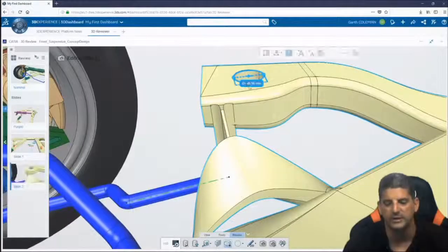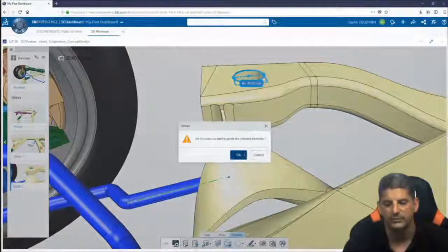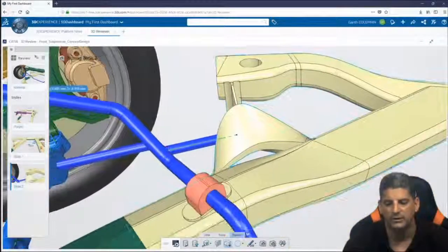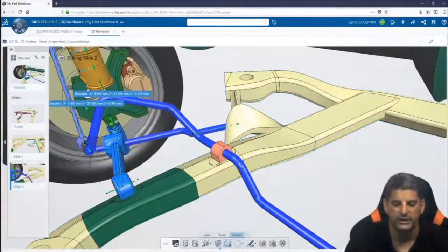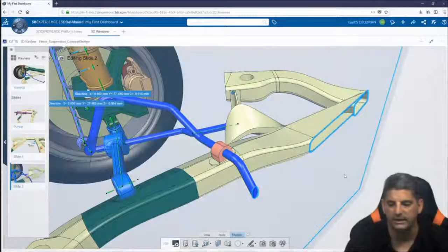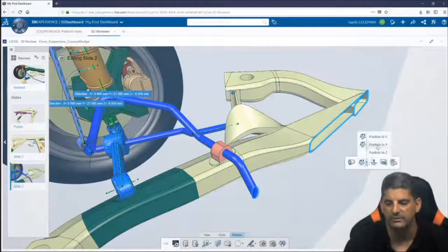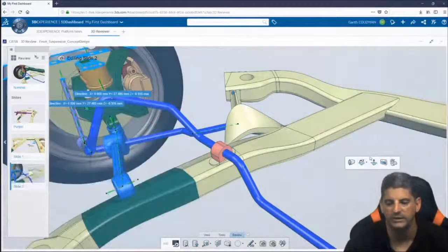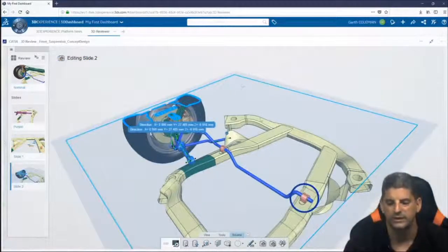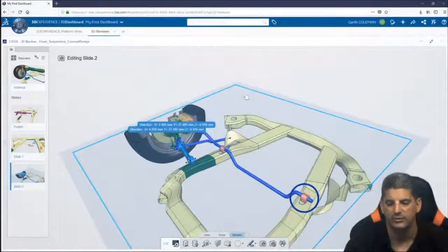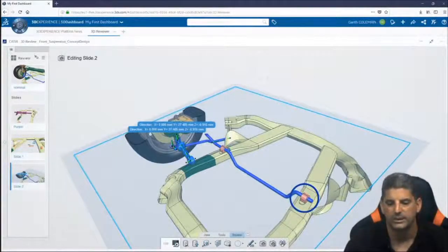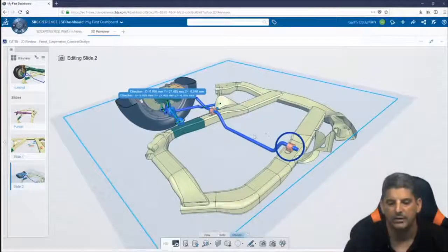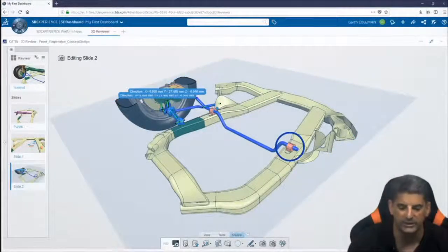Notice the approximate there. The other thing you can do, which might be interesting, is you can do sectioning. So sectioning is right here, this button there, section. And it's throwing a plane on there, and I can right-click on that section, and I can position it different ways, on the x-axis and the y-axis, or the z. Okay, so here I'll do the z, and I can kind of move it through. Now, if I turn off this, I can hit this button here. I can flip it, by the way.